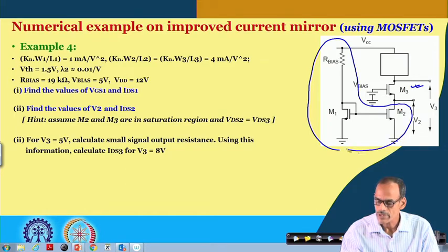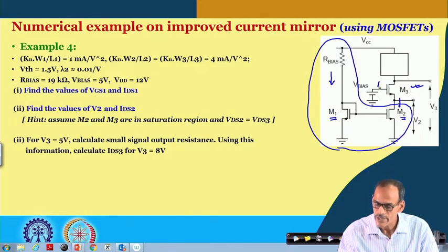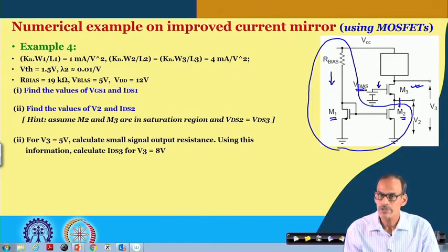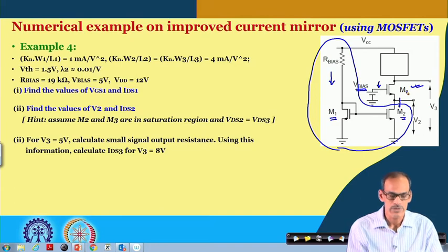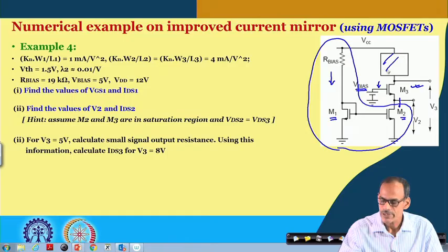The main current mirror is constructed by M1 and M2, and whatever reference current is coming, it is mirrored here. Then we have this transistor M3. To have meaningful operation of this circuit, we require its gate voltage, V bias, to be sufficiently high, so that transistor 2 and maybe 3 also are in the saturation region of operation. And of course, we have the application circuit here.